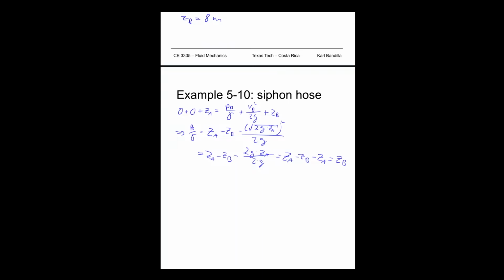All right, but we're not looking for a height. We still need to multiply this all by gamma to get our pressure. So PB, and I forgot a negative sign right here, because ZA is positive, ZA is negative, but ZB is negative as well. So let's not forget that. So we'll get minus gamma times ZB, which means we're getting a negative pressure.